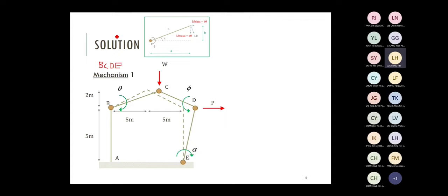And what should we do after that? Firstly, put the plastic hinge on the structures and then try to sketch the movement, right? The possible movement. It will help you understand how it behaves. And you can see that basically this region is free to move after formation of 4 plastic hinges. So totally flexible. We don't want this to happen.